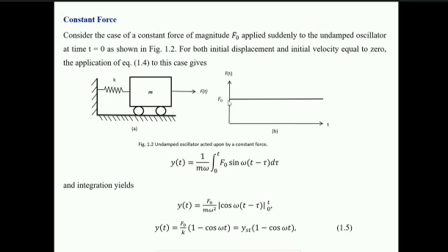But if you gradually put the weight, very gently, if you first touch the weight on the beam and then gradually lose your holding so that the weight is gradually transferred to the beam, then it is static loading. We are not very clear about what is static loading and what is dynamic loading. But if we just take the weight and suddenly leave it on the beam, it's a dynamic loading.